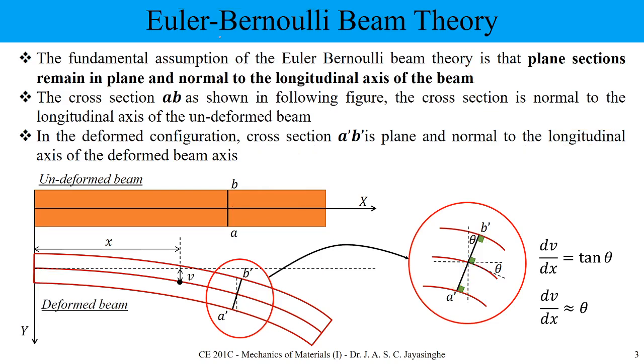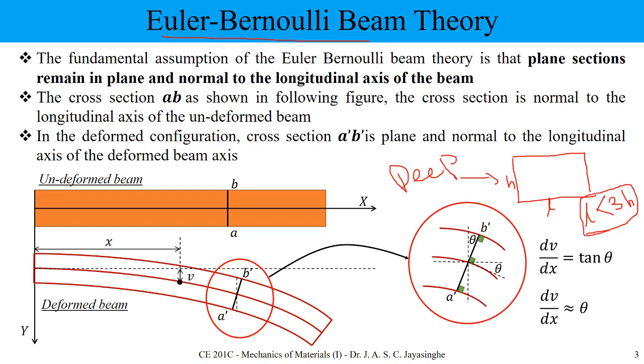And the next beam, this is a Euler-Bernoulli beam. So we got slender beams. The other one we call the deep beam. Deep beam. Here we are not going to touch this type of beam. A deep beam is actually a very short beam. Okay, so this is H and this is L. So at least think about L should be less than 3 times H, 3 to 2 times H. So if it's less than this type of thing, we call it a deep beam.